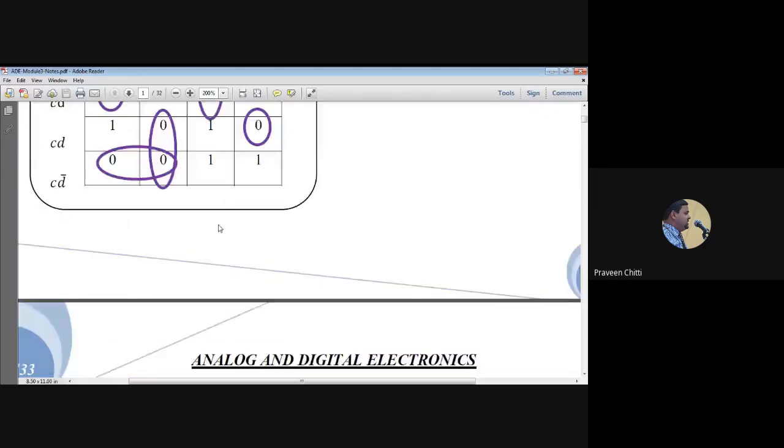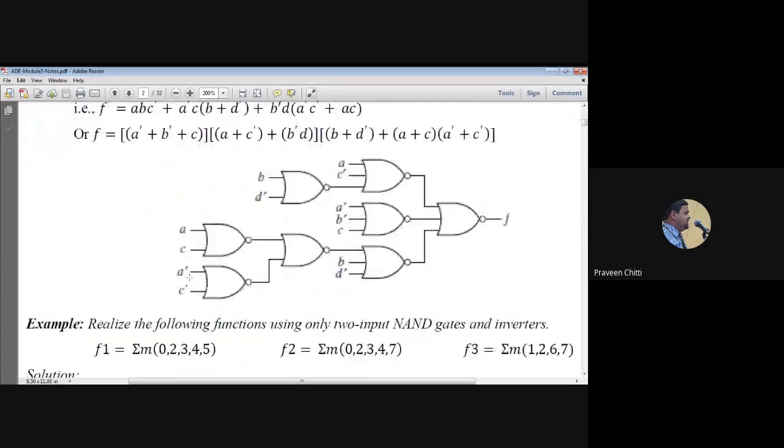So we need to do all these adjustments and simplification, and then you can get the 3. You can see here any gate which you have used in this particular diagram does not have more than 3 inputs, because the fan-in limitation here is 3. Right? I hope all of you understood this. All of you understood that? I know many of you have not understood it. That's why I will not go for this particular method of realizing any given Boolean equation using limited fan-in.